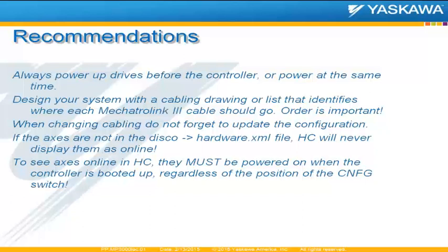There was one question about the timing of the power on sequence between the MPiec controller and the servo packs, but I think you had answered that question in your discussion just here about the controller taking more seconds to power up than the servo packs? Yes, that's in general. In general, I've found it's okay to power up the entire system at once because the amplifiers always come up before the controller. But if you want to make certain, you should power up the amps first.